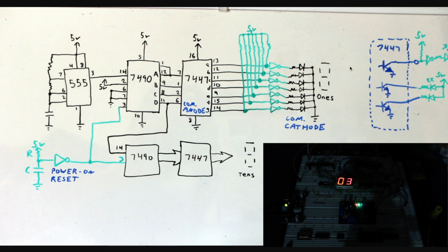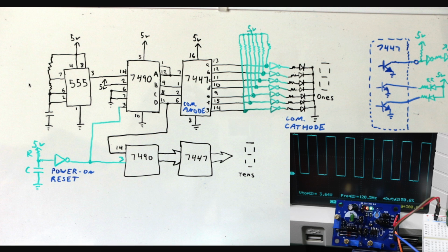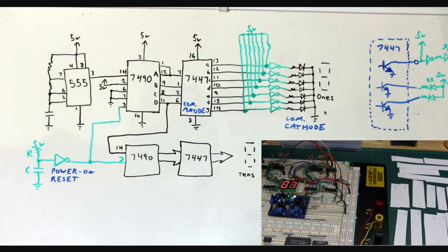Let's build a 7-segment LED display with 2 digits based on a 74LS90 and 74LS47 and clock it from a 555 dev board. Then we'll use this 2-digit counter to help us draw a winner for the 555 dev board.